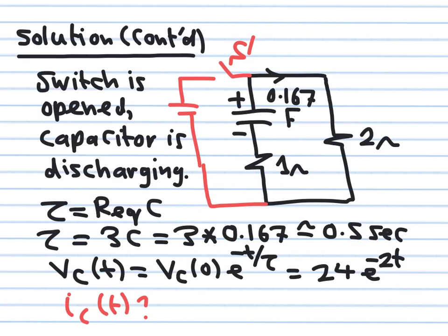So what do we have now? We have a capacitor that initially had 24 volts across it, and it now will start to discharge, like the first example we had in this video, through the 3 ohm resistor. Remember this 3 ohm. So I don't have to reinvent the wheel again. You can write the expression of the discharge very similar to the first example, but I know it's going to be a discharging curve from 24. So it's going to be 24 e to the minus t over tau, and tau is C multiplied by R equivalent, the total resistance seen by the capacitor.